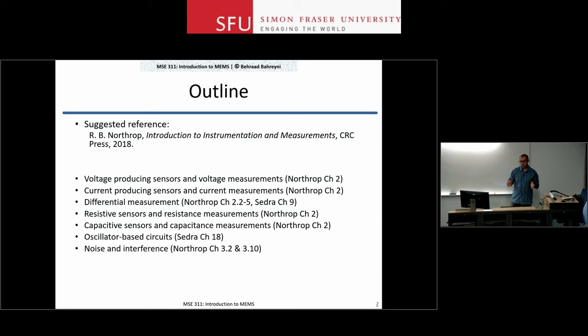We'll show you the sources of noise and then how to do noise calculations in the system that can have mechanical and electrical components. Once we learn about what noise is, we'll talk about a very important technique to do low noise measurements. So that's going to be a very simple case, but synchronous demodulation will let you have fairly low noise measurements even in a noisy environment.